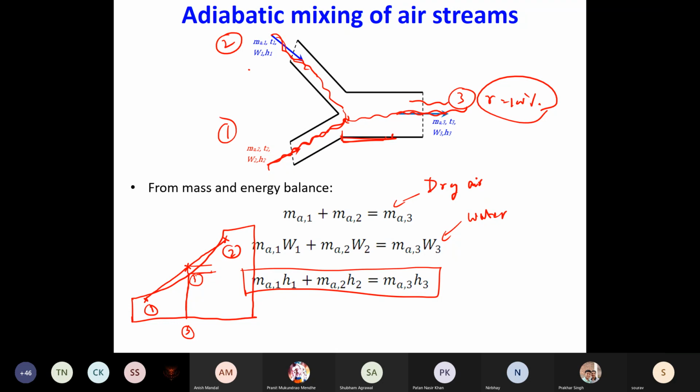Okay. So this is quite common. If you actually look at this mixing process, this is quite common in our home. If you have an extremely cold room, you have made it cold by using your AC, and you suddenly open the door or window, where the outside air could be hot and humid, then you can actually see water vapor condensing on your window grills, on your arms, on the floor. Because everything was cold inside. So state point 2 got mixed with state point 1 and it created an intermediate state which led to RH greater than 100%, which means that you will have condensation.